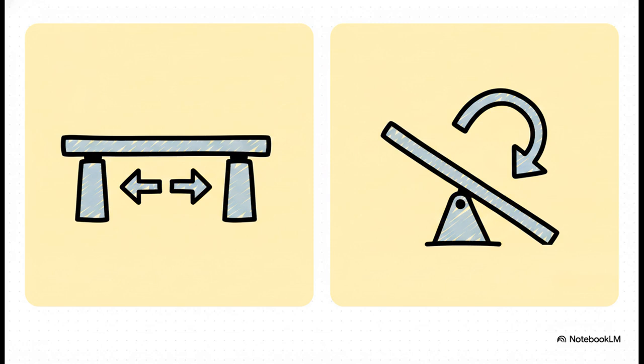But there's actually another twist here from multi-master setups dealing with different speeds, and that's clock stretching. Through similar open drain physics on the SCL line, the clock line, the slowest device can literally hold the clock low, acting like a giant physical AND gate to force faster masters to wait. It's just another brilliant way hardware physics silently controls the flow of data.